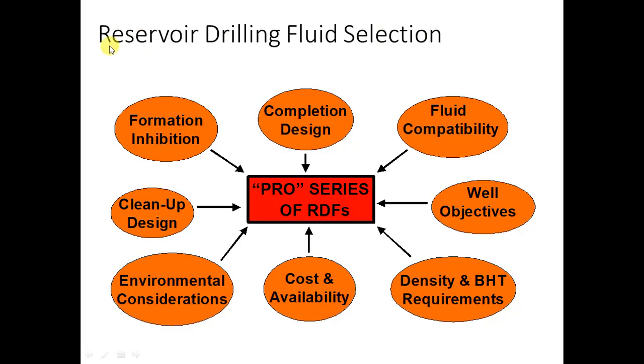So the reservoir drilling fluid selection depends on number one, the formation inhibition, number two, the clean up design, and I told you that the clean up design is very important due to the screens, especially in the open hole completion. Environmental considerations must be taken into account. Completion design, fluid compatibility to the reservoir, well objectives, and density and bottom hole requirements, and finally the cost and the availability must be taken into account.